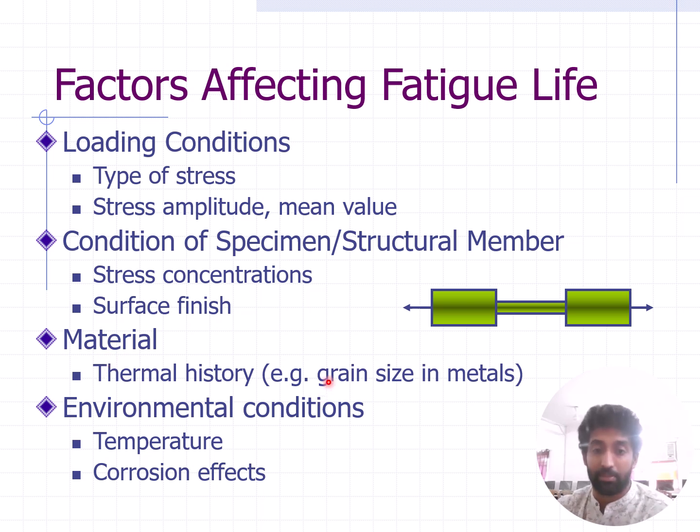Material factors like thermal history, the grain size, what heat treatment has been done, and what materials are being used. So that is what we discuss. Environmental conditions we have, like temperature. What temperature does it run at? Is it corrosive, like near the sea or not? So those are all the conditions we go through.